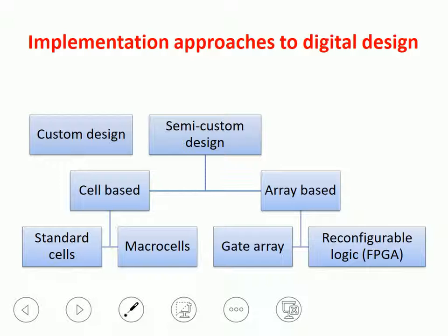So in the case of gate array, the important thing to keep in mind is that we have several logic gates already deployed in silicon, and we only need to design the interconnections. In the case of reconfigurable logic, we have, as the words say, reconfigurable logic that is already in place that we need to program and configure in order to let the circuit perform the operation that we want.